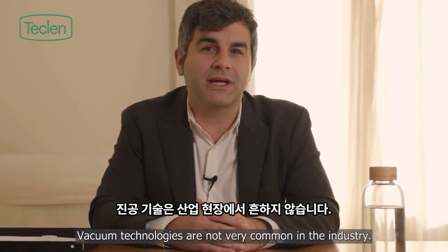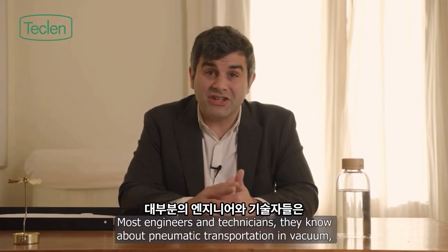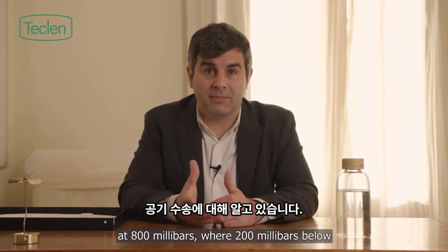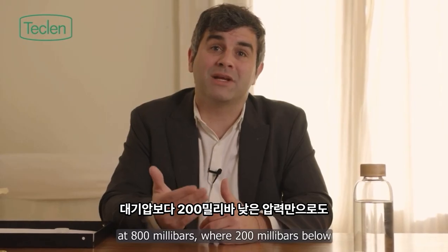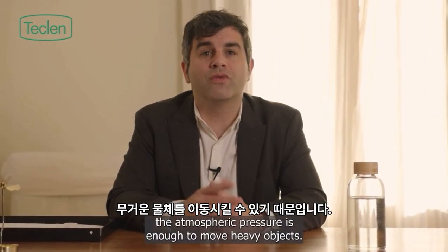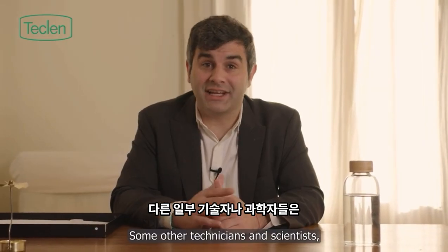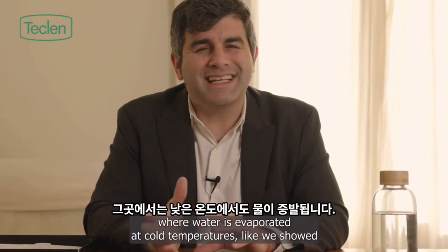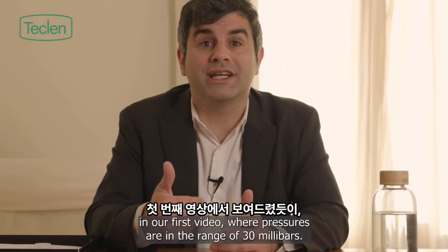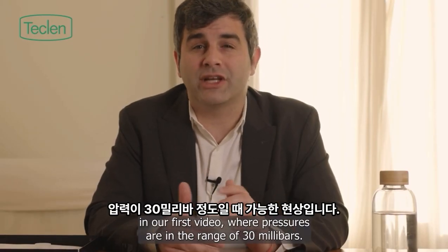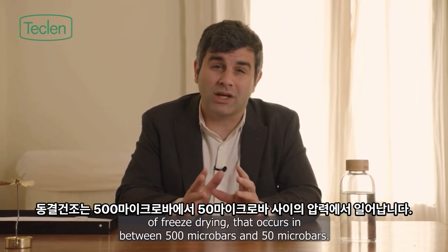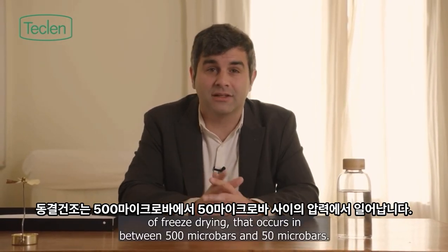Vacuum technologies are not very common in the industry. Most engineers and technicians know about pneumatic transportation in vacuum at 800 millibars, where 200 millibars below the atmospheric pressure is enough to move heavy objects. Some other technicians and scientists may know about other vacuum applications, like vacuum drying, where water is evaporated at cold temperatures, like we showed in our first video, where pressures are in the range of 30 millibar. But there are not many people who know about the pressure range of freeze drying that occurs between 500 microbars and 50 microbars.